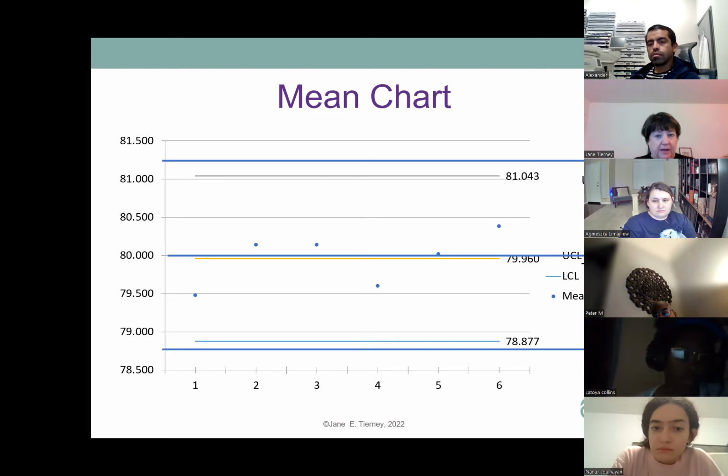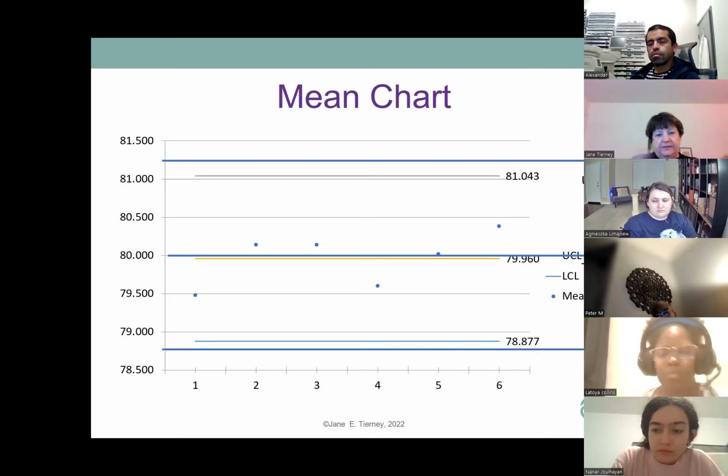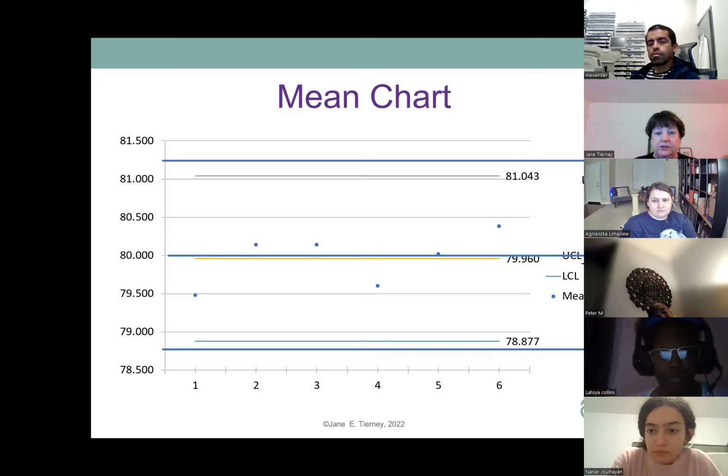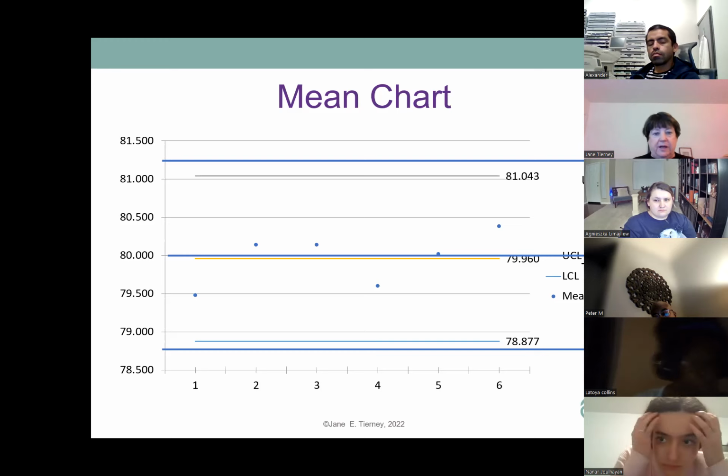Because you might think, okay, I'm going to have 200 parts, I'm going to take a sample of 12. If any of them are rejects, then I reject the whole lot. But that's not necessarily so, depending on what level of quality you want. So there are charts that you can look at to say, if I want this level of quality, I need to take a sample size of this, and the number of rejects I can have in that size is 0, 1, 2, 3, whatever it statistically comes out to be.